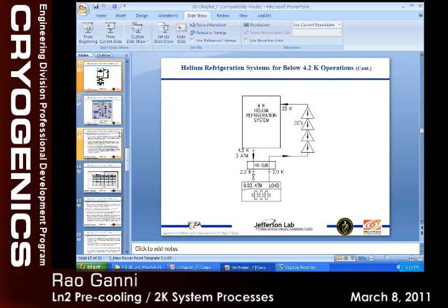If it is too hot a gas, for example after a trip or anything, our return flows from various transfer lines increase, and if the gas is coming too hot, it will reduce in flow. So the flow change is a very strong function of this temperature, which is normally running around, say, 3.5 Kelvin. It can go as high as 4.5 or 3.2. And it's proportional, the flow change for a given speed. Any sudden change in this temperature is the one that causes the trip. So all the processes, it can be another linac, another cryo module, some JT not acting right, or the controls froze up. That's most of the time where it starts.